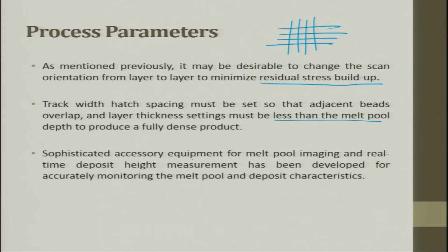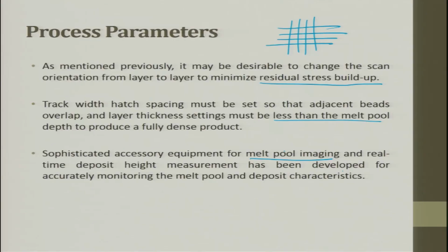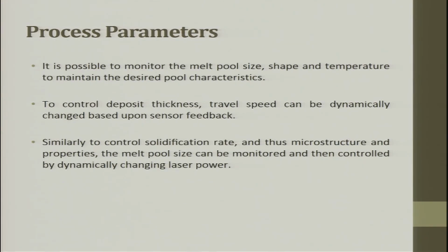Sophisticated accessories and equipment for melt pool imaging and real-time deposition height measurement have been developed. What is the temperature at the melt pool? Because if there is a larger melt pool, this is going to create more melting and solidification, and we have to now balance it. And the other thing is, whatever melts, when it solidifies, it does not give you uniform height. So, we need to measure the melt pool temperature using imaging techniques and measure the real time height, so that we know what powder flow is to be given.